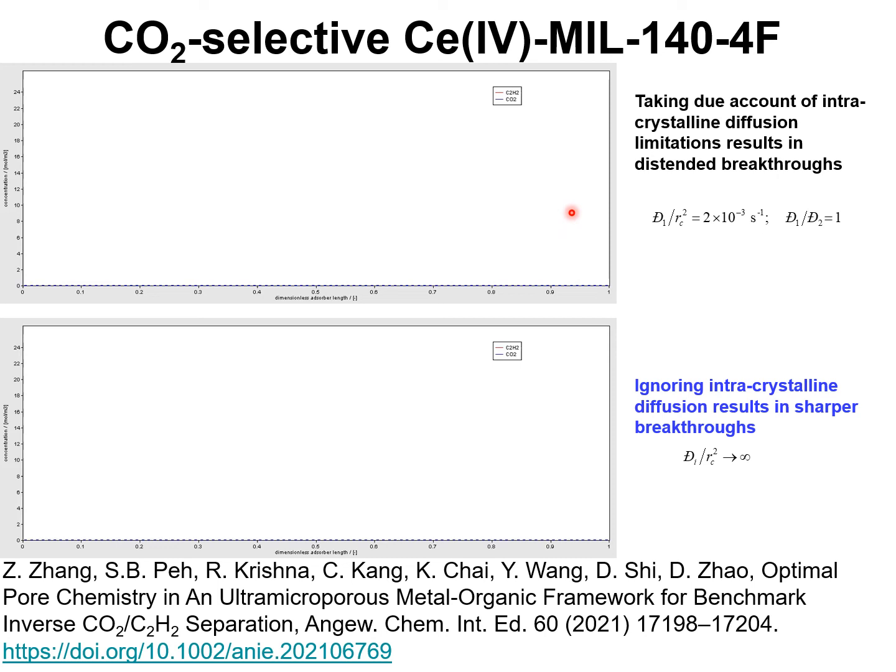We present simulations of transient breakthroughs in a fixed bed packed with the cerium MOF. Two types of simulations are compared, one in which diffusional resistances are duly accounted for, and the other in which the diffusional effects are ignored, and we assume that the diffusivity divided by the square of the radius of the crystallite is very large, leading to practical equilibrium between a gas mixture and the particle of adsorbent at any position in the fixed bed.